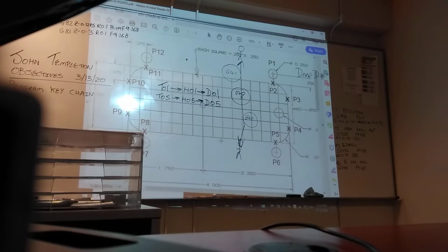The wear column. To the right of the tool geometry column is for any adjustments you need to make. So you use the wear column to make any adjustments you want to do. And the machine will take these two values, add them together, and use the one value. Right?